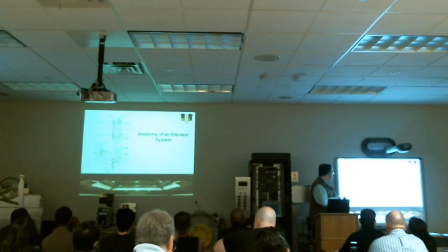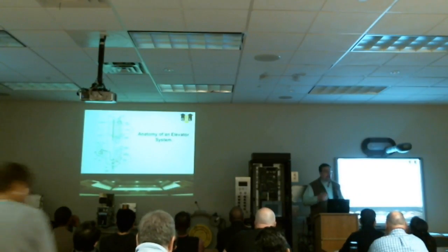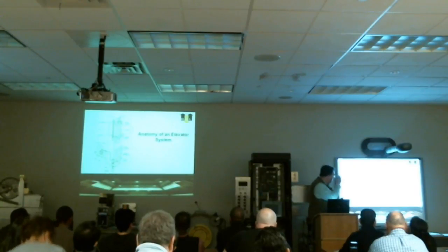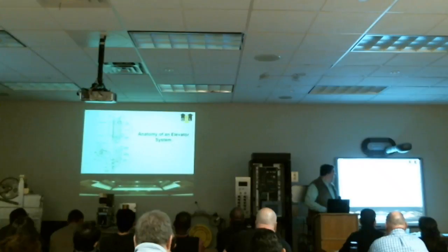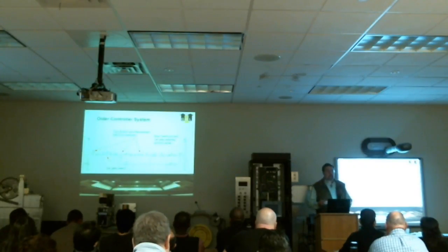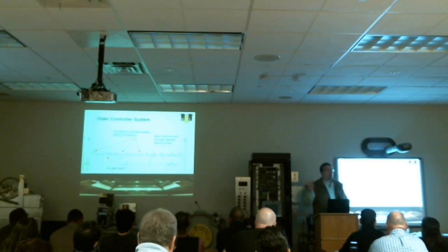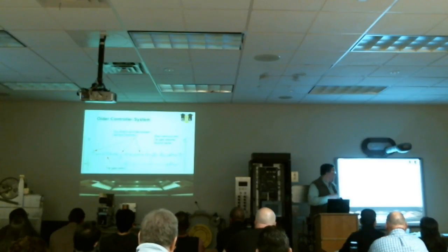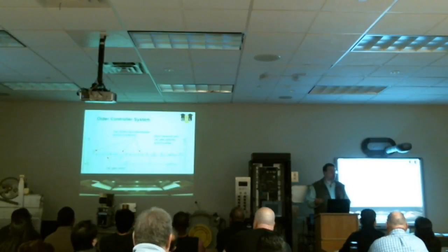So there's a switch on the car door side, and there's a switch on every landing in the hall to tell us if the doors are open or closed, allowing us to safely travel, among other signals the elevator is required to have. On old control systems, they didn't really care. Everything was pretty much monitored in what's called a string fashion. All the door locks, interlocks, gate switch, everything was monitored in one string for the controller. So once all of them have been made up, it says to the elevator controller, hey, the doors are closed,